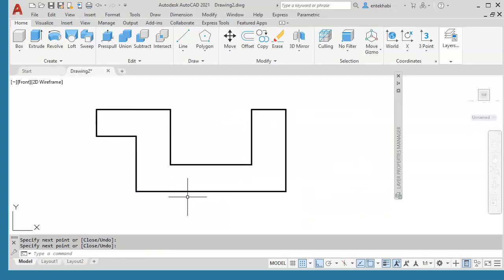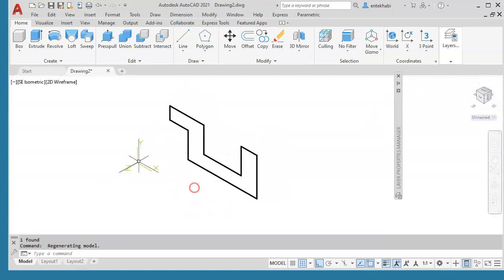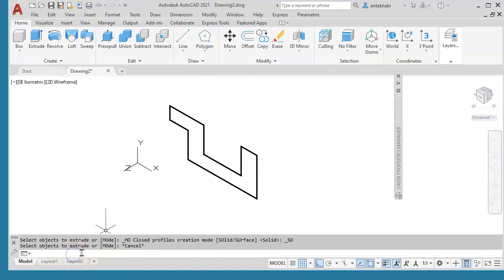Then make sure that all the dimensions are correct. And the next step is to use the extrude tool. But before, let's see. Yeah, we actually need to, this would create a surface model. We need to use the join first.